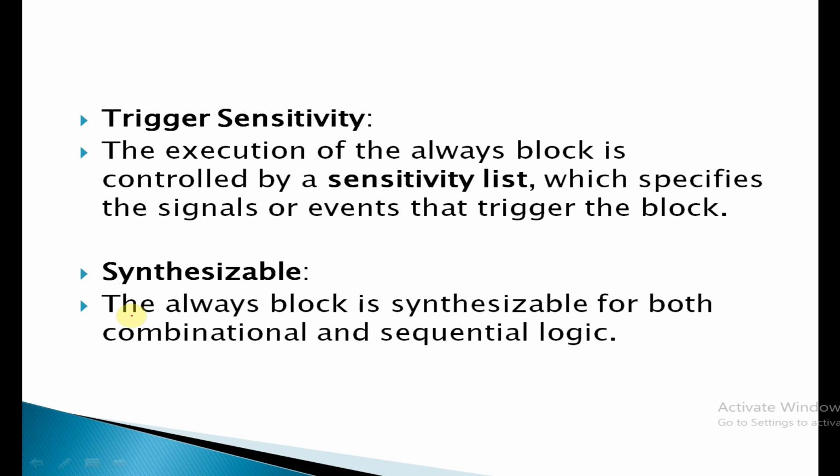If there is any change in that particular list only, the always block will be triggered. Unless there is a change in that list, it will not be triggered. The always block is a synthesizable construct.